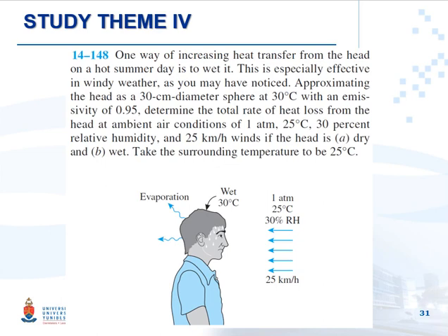First, finding the properties, calculate the Reynolds. From the Reynolds calculation, you can have an understanding of what kind of flow you are talking about, if it's laminar or turbulent. After that, you can go and find the right correlation for Nusselt.